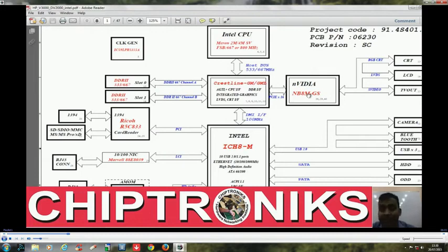We require NVIDIA or ATI graphics for graphic-intensive purposes, since graphic-intensive applications require parallel processing, and these graphic chips have a GPU core, graphics processor unit, so they can process those applications very easily. But this GMCH has an integrated display controller. That's why it's written LVDS and CRT.